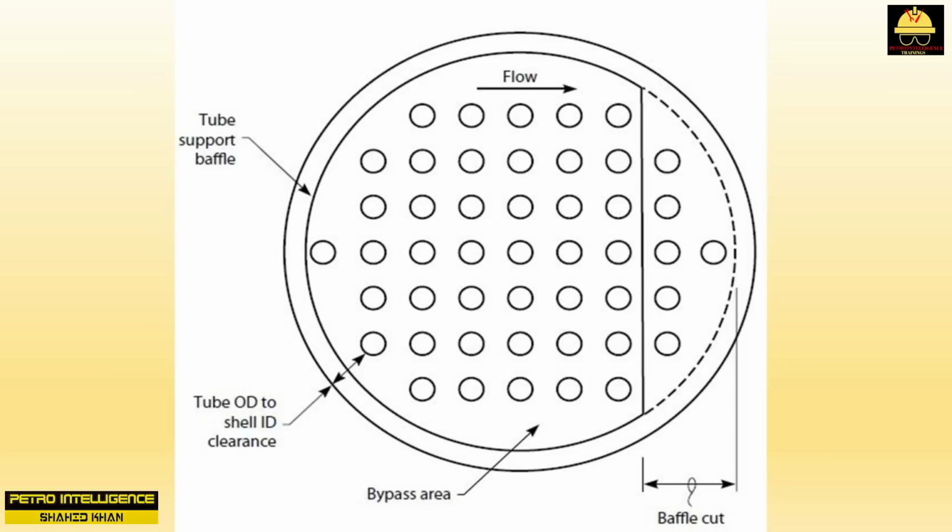It is the primary purpose of the seal strips to reduce this gap. For the seal strips to fulfill this function, one of the seal strips in each pair must extend the full length of the tube bundle. This is rather complicated to explain. However, if you look at a tube bundle that has been extracted from its shell, you will understand why this is needed, and how impingement plates render seal strips essential for good sensible heat transfer from a shell-side fluid.